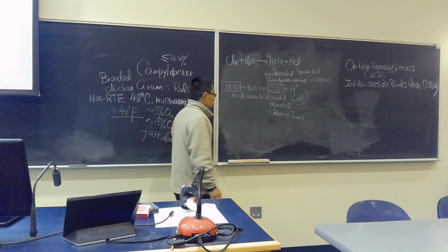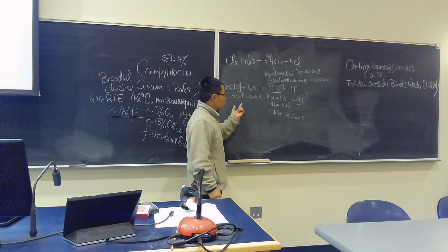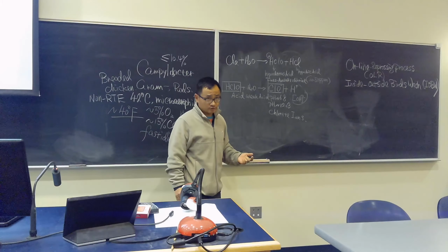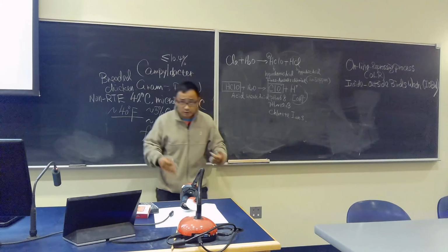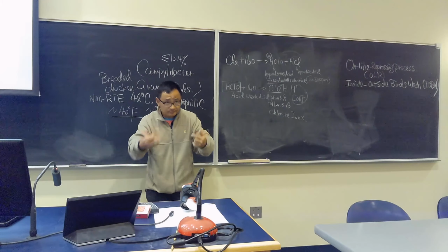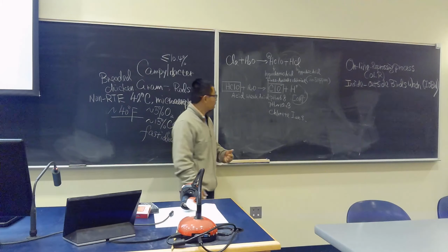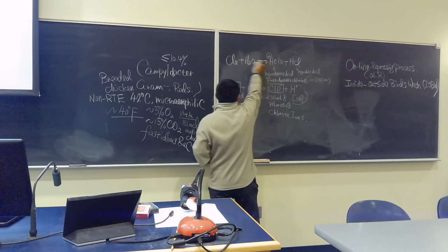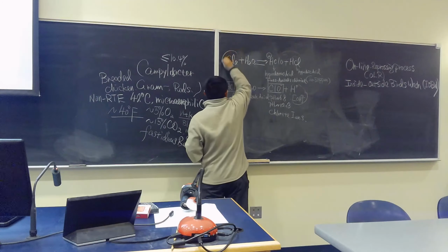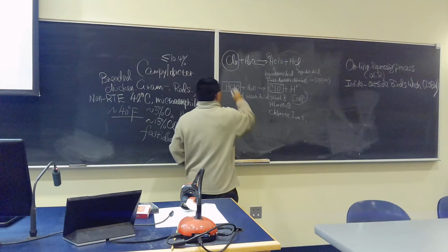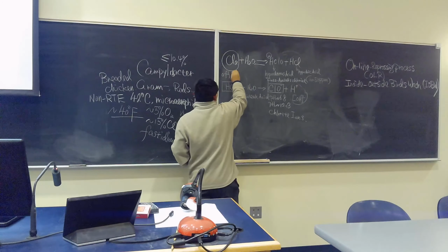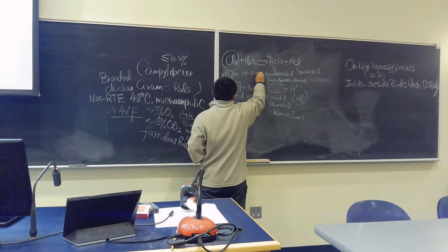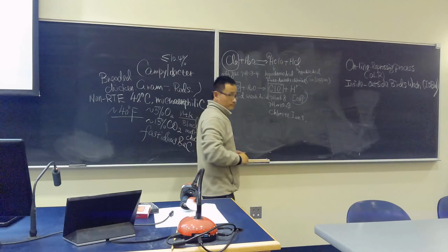So, what's the key? Control the pH. It has to be around 6.5, 6.8. But some people are going to say, can we just keep adding acid? No, you cannot do it. If you keep adding acid, what happens? This kind of reaction goes here. This will be more generated, become what? Off gas. If you are doing pH 3 and 4, the off gas is generated.